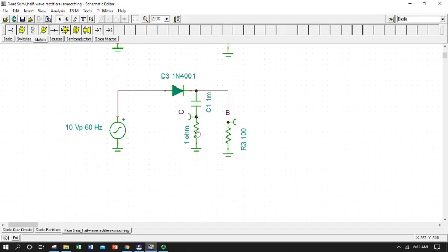So the current in amps flowing through this resistor is exactly equal, because the resistor is 1 ohm, to the voltage drop over it. So my voltage C relative to ground that's going to plot out when I do my analysis is going to literally tell me the current flowing through this resistor, which is also the charging current of the capacitor. I'm going to get positive current coming out.